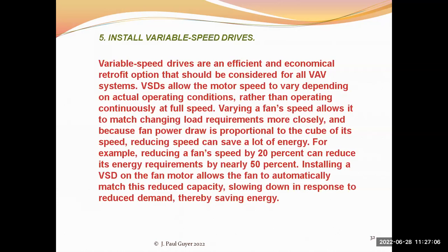the control system adds up all of the quantities of air that are being called for, and then it reduces or increases the speed of the motor, which increases or reduces the speed of the fan as required. And this results in a substantial improvement in the comfort performance of the VAV systems and in the efficiency of the utilization of energy.